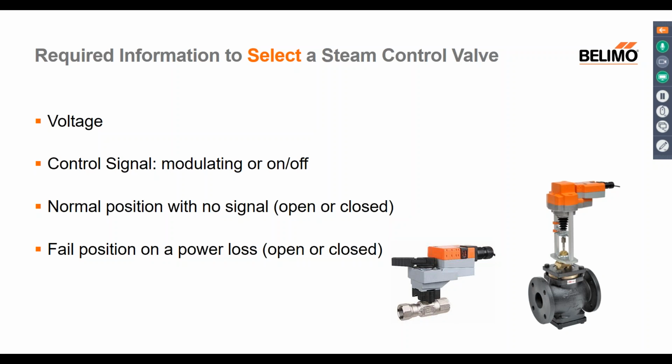That's not cut in stone anyplace. That again is just a rule of thumb. Heat exchangers, steam to hot water heat exchangers, generally always fail closed because you don't want stagnant water and let the steam valve run and cook out the heat exchanger. So again, these are just rules of thumb, but they're good rules of thumb that the industry generally follows.